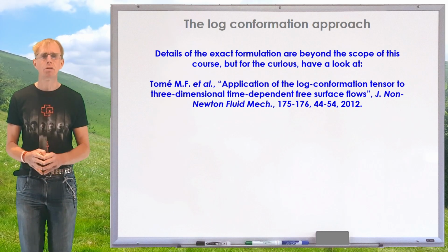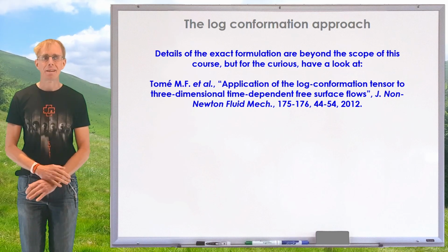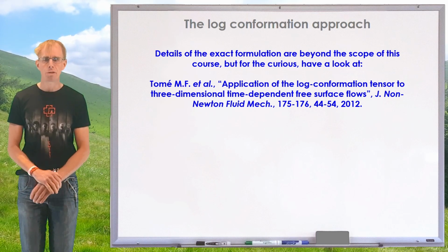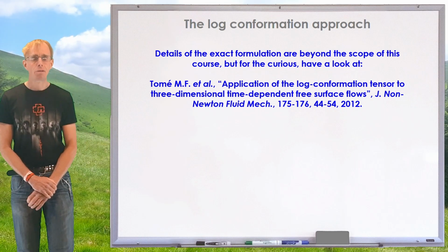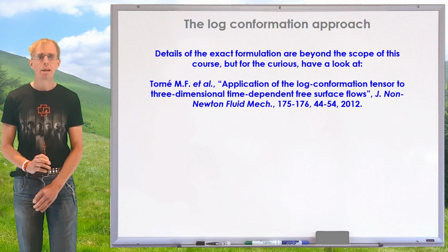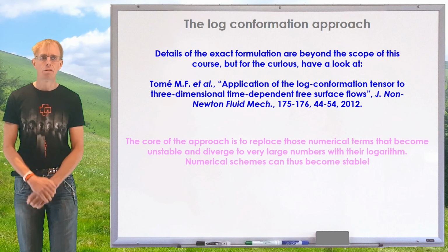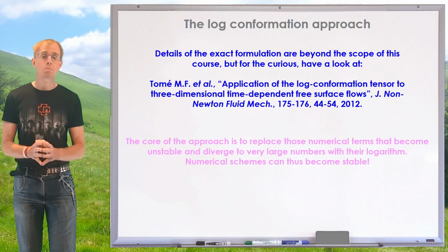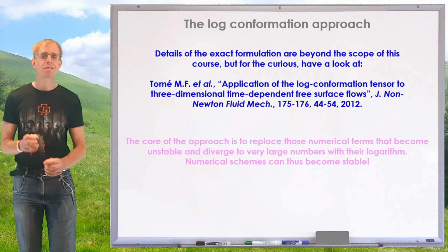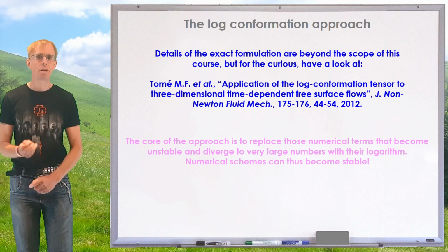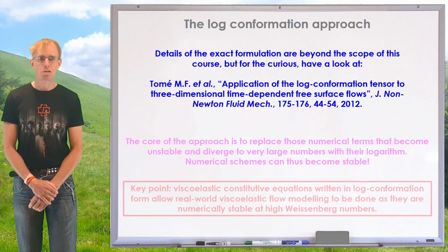It's possible to redraft many of the popular constitutive equations in log-conformation form. Again, the details of this are way beyond the scope of this course, but for the curious, I've put a reference there to go and have a look at. It's very mathematics heavy, but the net result is that you can get stability numerically at high Weissenberg number. So, with suitable compute power and with log-conformation formulation, it is becoming increasingly tractable to start to numerically model engineering type flows containing viscoelastic liquids.